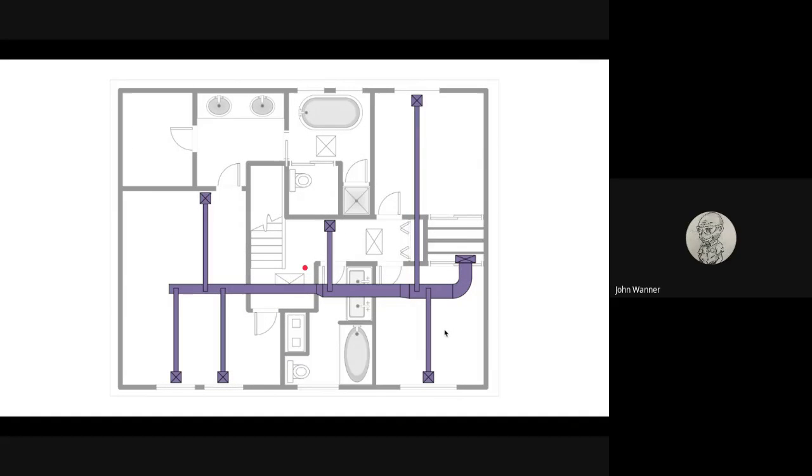Next, we're going to talk about heating and air. It's all known as HVAC, heating, ventilation, and air conditioning. This, again, looks like a small 2-bedroom apartment, a 3-bedroom upstairs apartment, because here's a set of stairs. I orient myself to the type of the room. And then I look, and this purple here, this is the main ductwork that's going to distribute the air throughout the building. These squares with the X in them, those are the air registers.